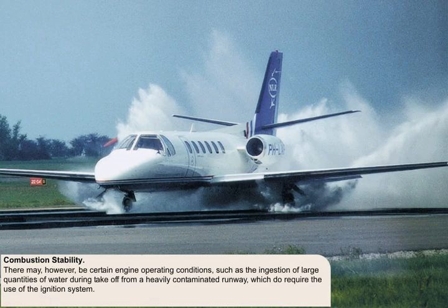There may, however, be certain engine operating conditions which do require the use of the ignition system. For instance, just such a condition would occur following a flame-out, which is extinction of the flame due to various unusual occurrences, such as the ingestion of large quantities of water thrown up from the nose wheels into the engine intakes during takeoff from a heavily contaminated runway.